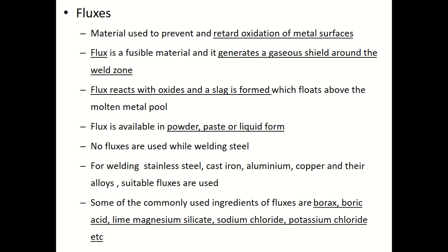The flux is a fusible material and it generates a gaseous shield around the weld zone. What is happening here is that the flux reacts with the oxides and a slag is formed, and the slag floats above the molten metal pool. In the market you can buy the flux in powder form, paste form, or liquid form.